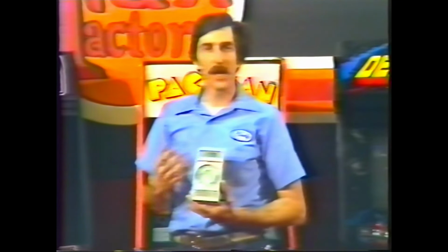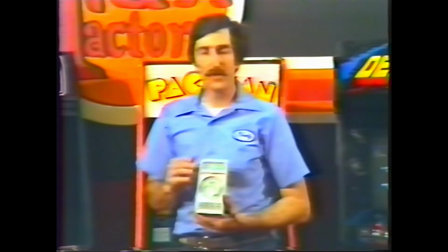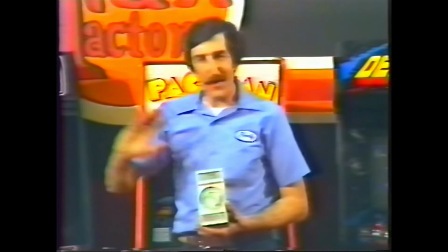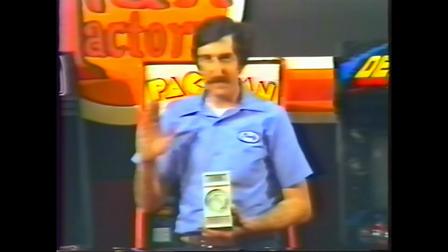And like other digital multimeters, this particular meter can be used to measure AC and DC voltage, AC and DC current, and resistance. There's also a very special range on this meter. It's called the diode test range. By using the diode test range, which is built right into the meter, we can test diodes and transistors without having to buy a separate piece of test equipment to do it. During this lesson, we'll be taking a look at the digital multimeter and effective ways to use it to repair electronic games. Let's take a closer look at this extremely versatile piece of test equipment.